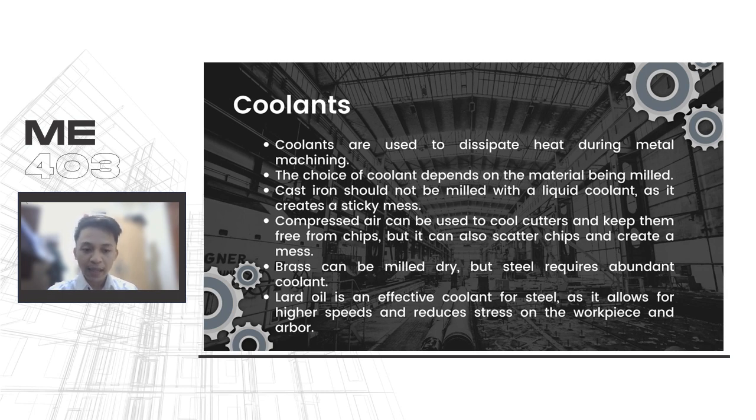Cast iron, milled at typical speeds and feeds, doesn't overheat milling cutters and should not be used with a liquid coolant, as it creates a sticky mass when mixed with cast iron chips.